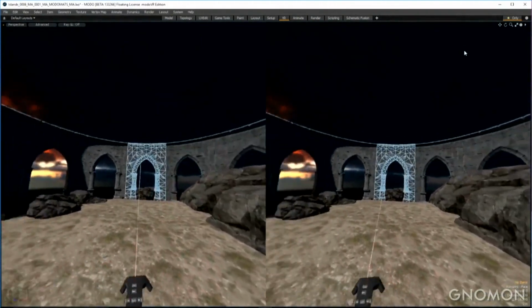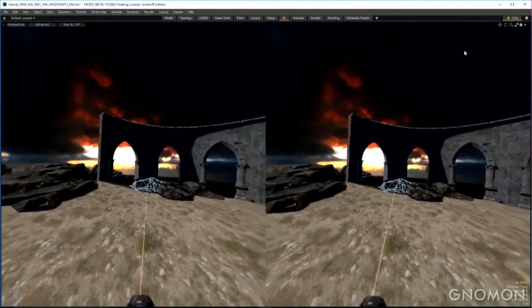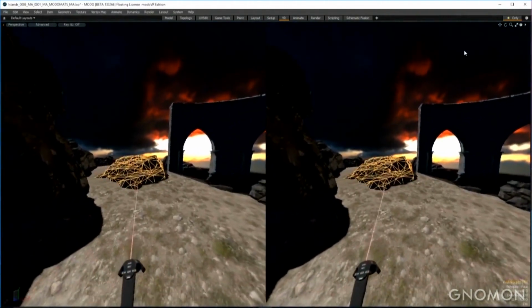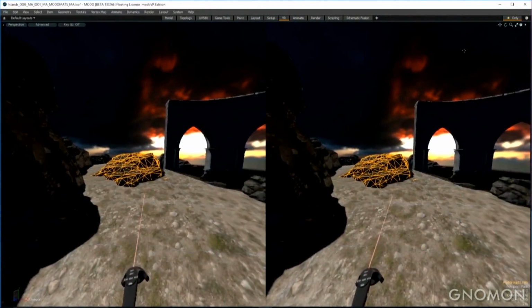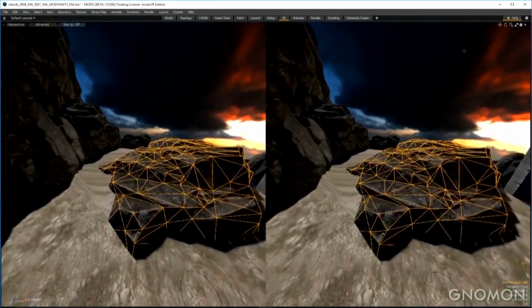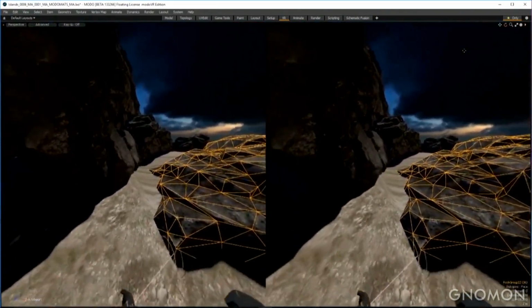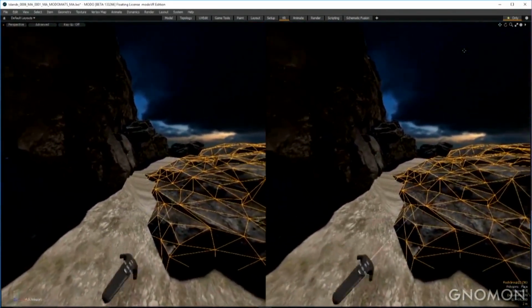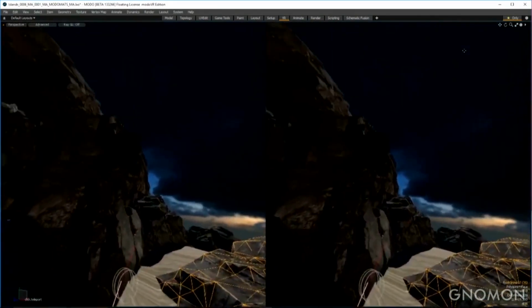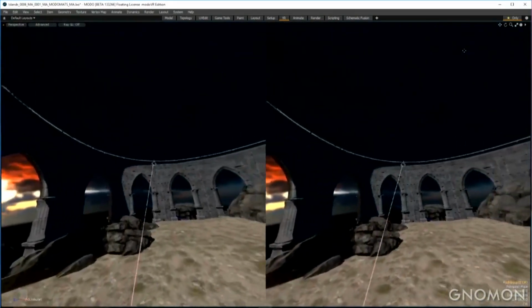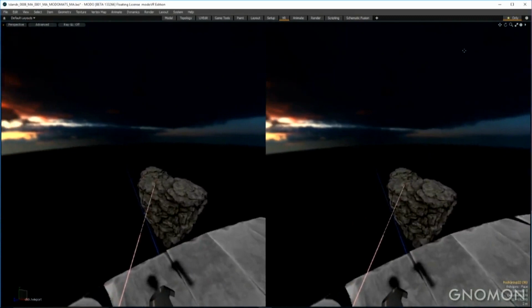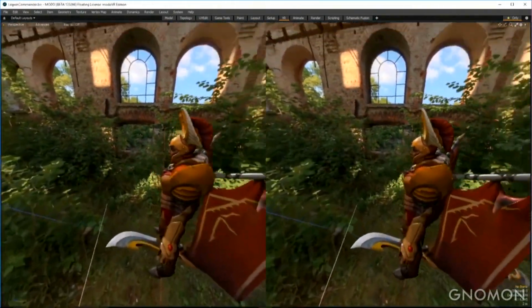And I can select items, check out their wireframes, which is massively important for VR experiences, teleport over, take a look at that wireframe. And yeah, there we go. There's a perfect example of a problem. I've got some texture stretching right in that corner. Probably want to fix that after the fact. But I'm evaluating this by walking around, teleporting, and interacting at real-world scale, which is wonderful.